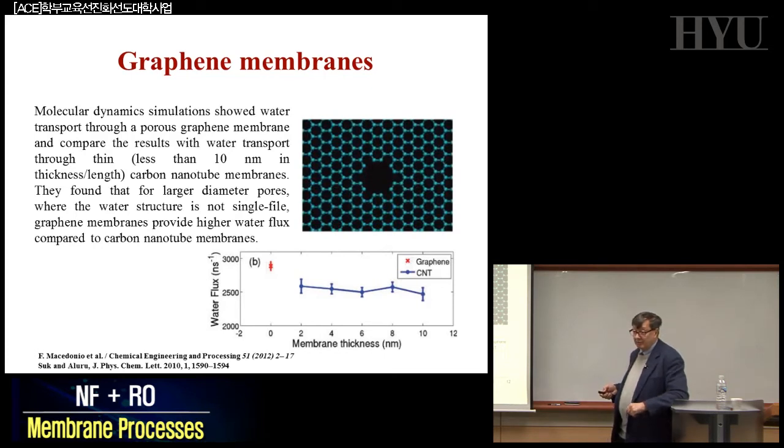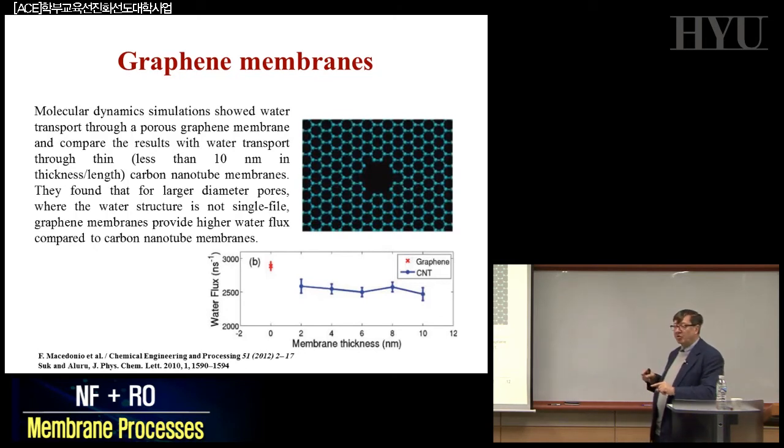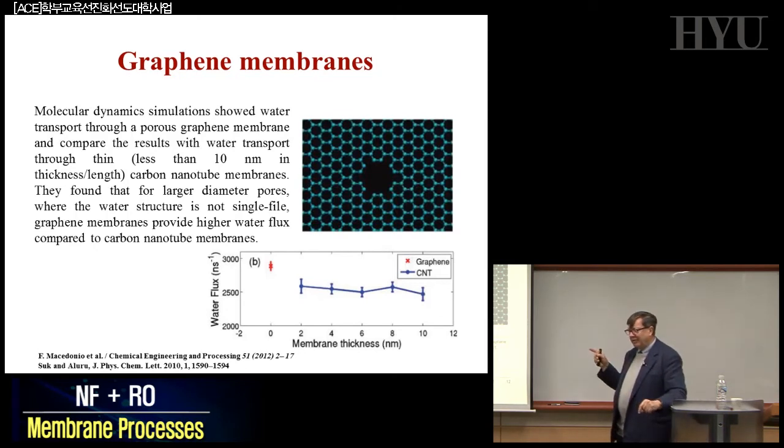full of defects. A lot of perovskites are a mixture of different metal oxides normally. In the crystal, if there is a defect, a vacancy of oxygen, you have just a possibility to have oxygen entering, jumping into the vacancy. There are many vacancies, and you have oxygen jumping from one vacancy to the other. So you have 100% selectivity only for oxygen. The trouble is that this kind of phenomenon is, until now, activated at high temperature, at 800, 900 degrees centigrade.